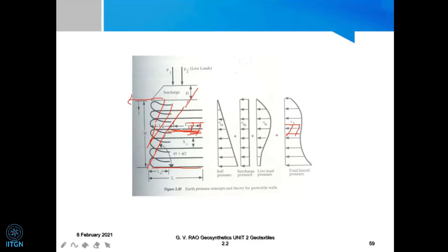And mind you, when I say area now, we are getting this line now. We are using 1 running meter across it now. So exactly what we do in normal retaining wall only. So we got this line length here of the effective length. Effective length means the total length is L here of the reinforcement. But then effective length is the length beyond the failure wedge now, which is going to resist this. Okay?